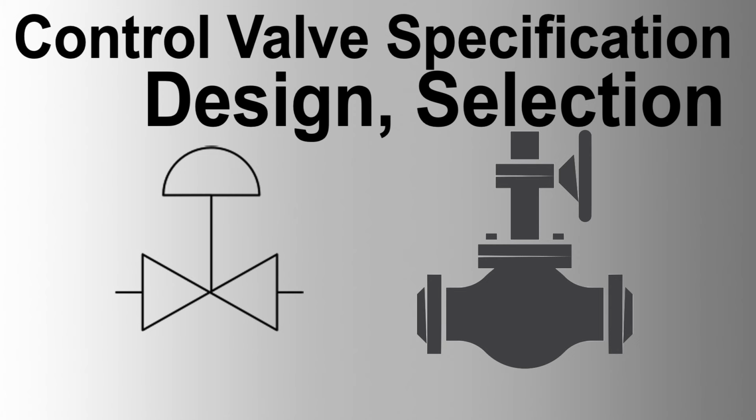11.2 Pressure drop considerations. For high pressure drop applications, consider angle body valves or low noise labyrinth trims. Ensure valve can handle 150% of normal flow or 110% of maximum flow, whichever is higher. For two-phase flow, consider CV for both liquid and vapor phases.